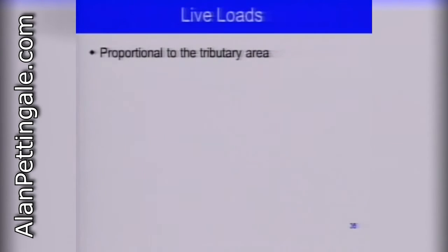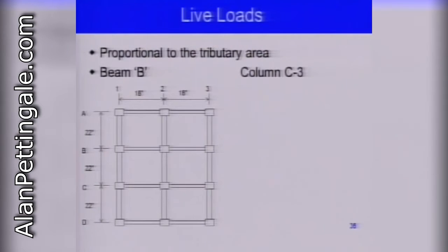Then the other types of loads, you can have snow, wind, flood, blast, earthquake, and there are provisions to calculate the loads for that. So it might look funny mentioning snow or earthquake here in Brownsville, but you will actually see that there are maps in that document that give you a load. That's usually very low, and the design would be governed by the wind in this case. That would change in California. But people need to be aware of that.